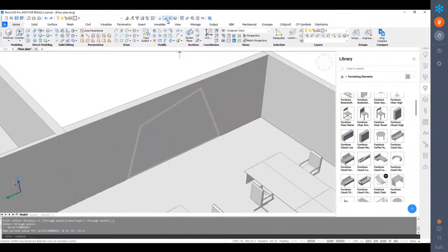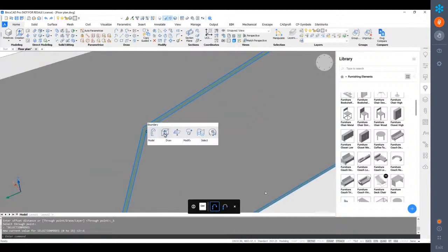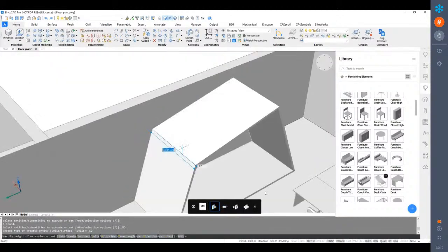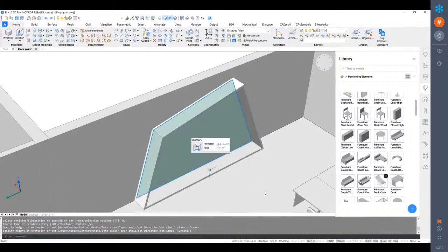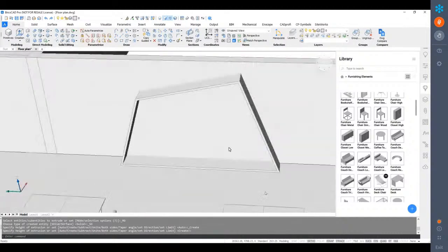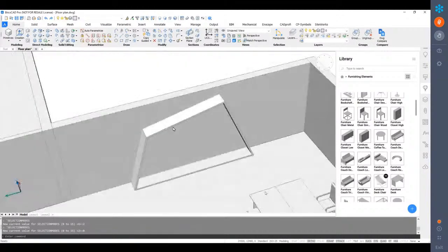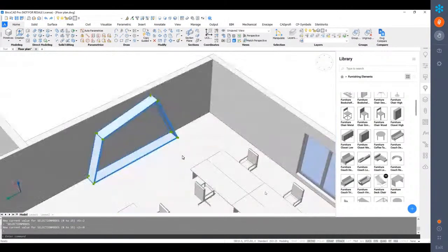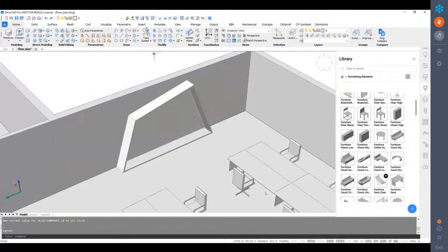Because we had the boundary detection tool, I can immediately get this boundary as well. And also, again, immediately extrude it out and create a new solid out of this. So it's not going to be attached to the wall. So let's say for this shelf, I just wanted to have a 450 shelf. That's good enough for me, perhaps. So I now have something like this. And you see, this is actually a separate solid from the wall. We just used the face of the wall as our guide face basically.